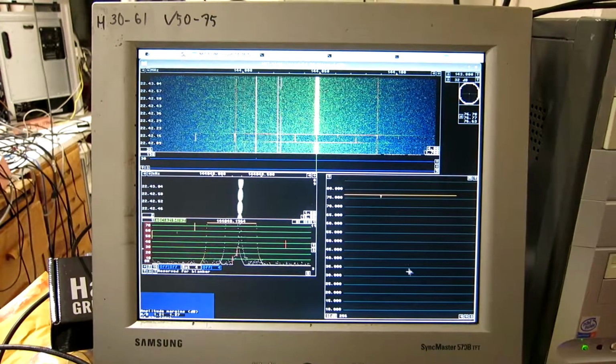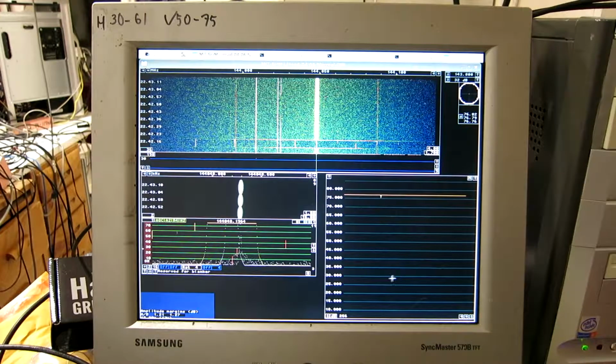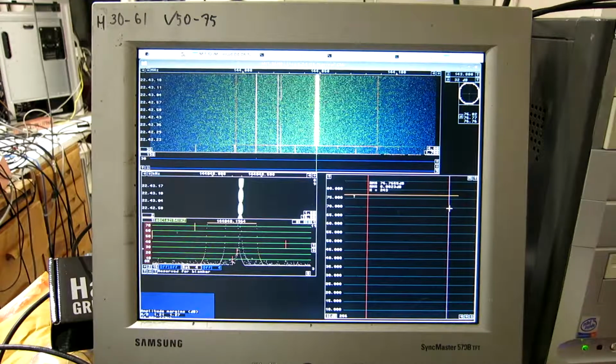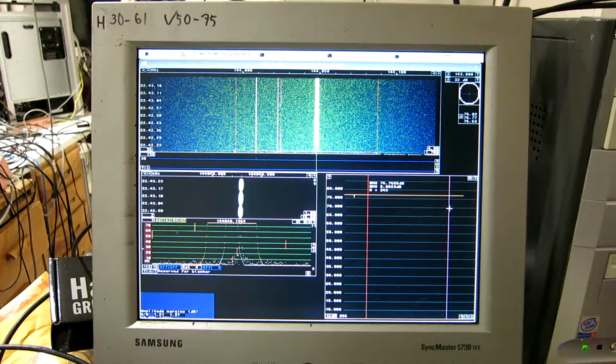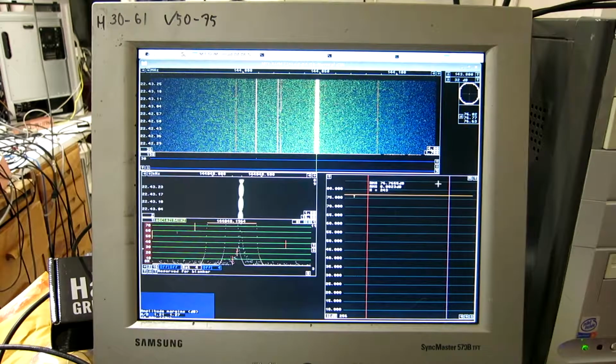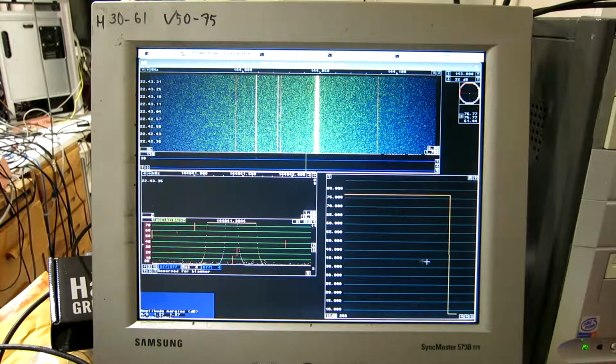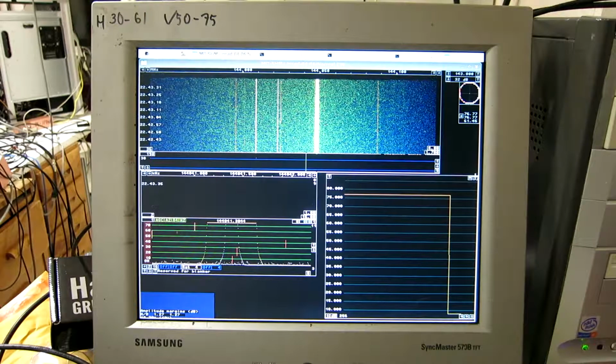Now I have injected a good quality crystal oscillator at 144.048, and the level is 76 dB, 76.7, and then I look at the noise floor close to it, let's say here, and it's low.